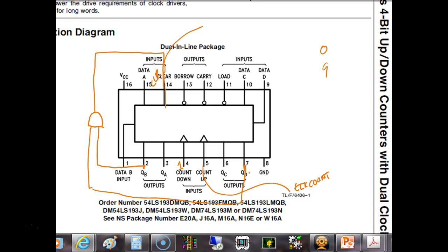So what did the PLC have to do? Well, we call them high-speed counters, and those are basically hardware. Those are built into the PLC. So they had to go back to hardware counters because the software counters couldn't keep up with it. So you're still going to run into discrete digital circuits, even though we're moving into a lot of programming, because programming software is slow compared to hardware. So the advantage of hardware over software is that it can be a lot faster.